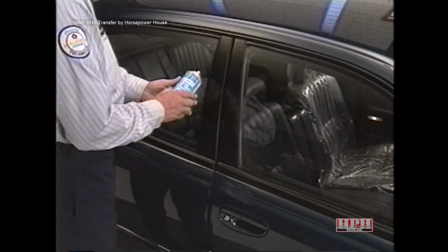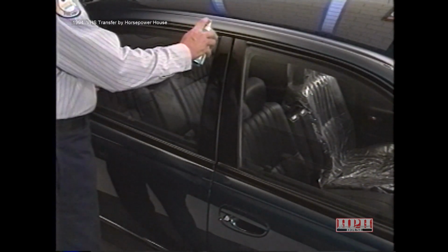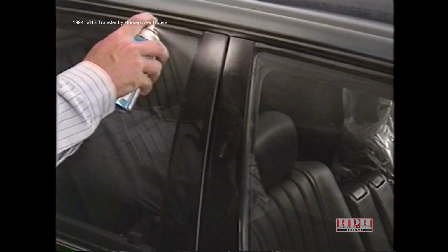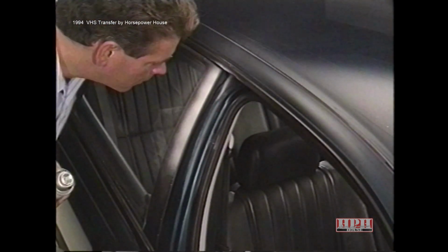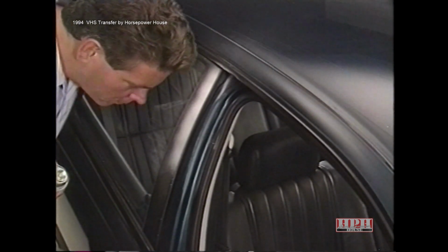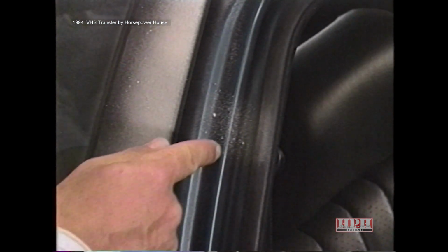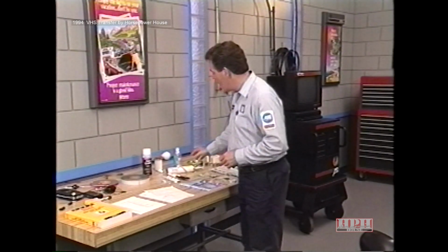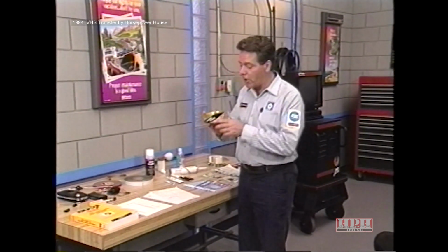Begin this test with all of the doors and windows closed. Using your spray can or bulb syringe, blow the powder on the outside of the questionable seal in the reported noise area. Then open the door and check for traces of the powder on the inner side of the seal. Powder that gets past the outer seal will pinpoint the location of the problem. Again, if the powder doesn't seem to be sticking, a light coating of paste wax on the inner seal may help.